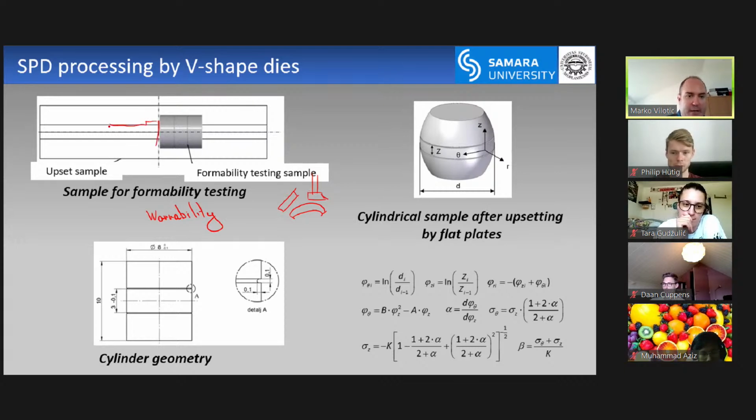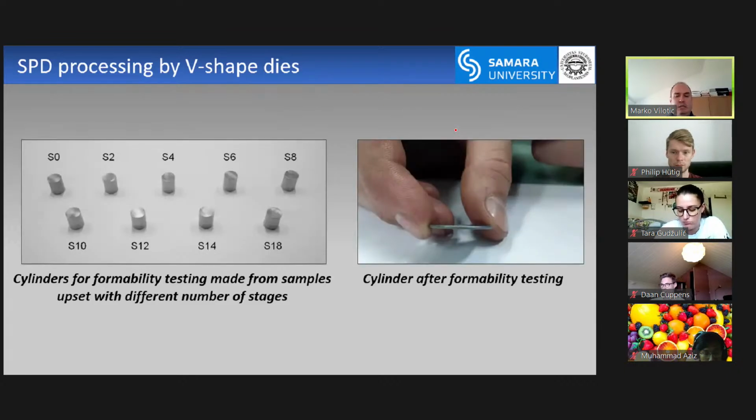So this is the part. In this part, I made tensile testing, right? You remember the tensile testing specimen. In this part, I made samples for the workability testing. It's just a normal cylinder, and it has these lines, these inscriptions, and when we compress it, we expect some material failure to appear in this area. It's unusual for the metal defect to appear here. It's usually here, and that's why we use this, so we can measure the strain, and we get these results.